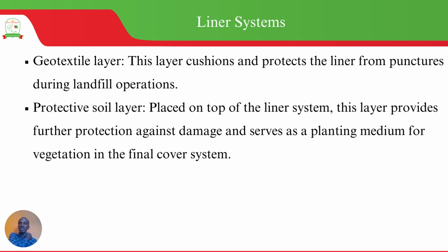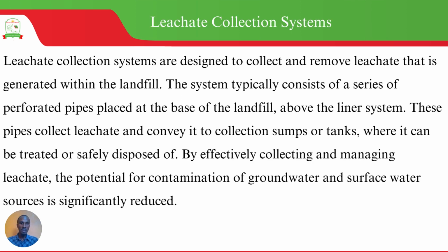So in that final cover system, we have this protective soil layer, which will make that landfill more stable and less susceptible to wind blowing away some of that waste, or running water also taking away some of that waste that we don't want to run off to the nearby water sources.